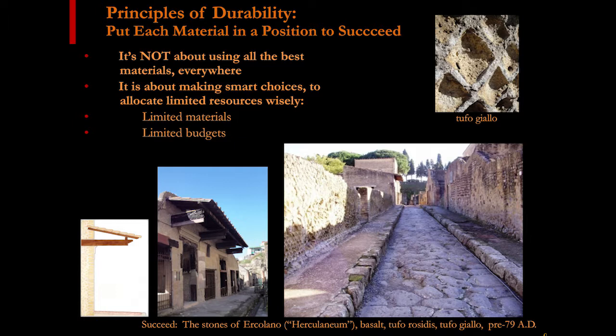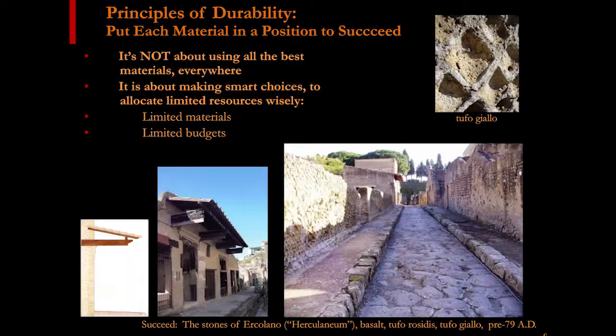kind of like our Portland brownstone that the Back Bay has been dealing with for years, repairing and restoring and refacing. And this is it right here. It's a very beautifully colored yellow stone. Here's a close-up of that wall. So this was only excavated about 1920. This building, unfortunately, no longer has the overhanging roof to protect it. And this kind of looks like bad repointing that's spalled off the stone. That's actually original Roman mortar, and this stone is so non-durable that it's essentially lost a durability contest with the mortar that was used to put it in place. So nothing wrong with that mortar, it's just a terrible stone.